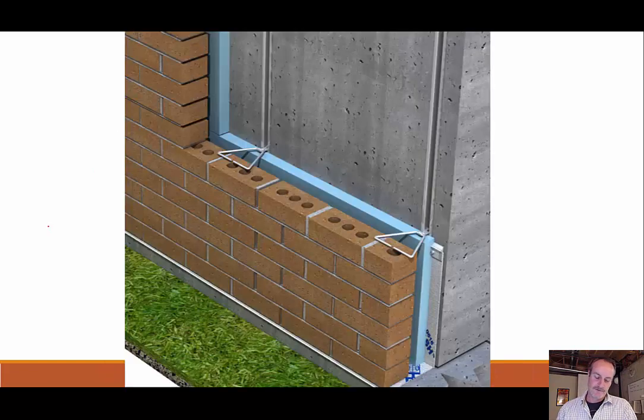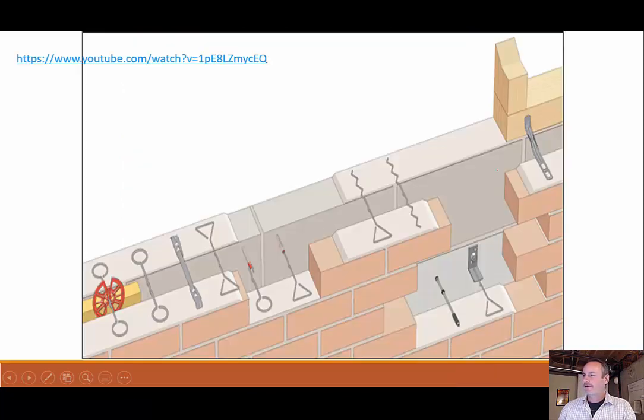So for example, here's a picture of one. This would be a dovetail anchor because I can see that there's a slot in the concrete, and then this looks like it gets a little wider and that holds it in place. Then when I put on my next course of brick, this would all be tied in, right? So providing that strength. And this would happen every so many courses up the wall to provide that strength from pulling away from the wall, give it that latitudinal strength. And we can see a couple other anchors along here.